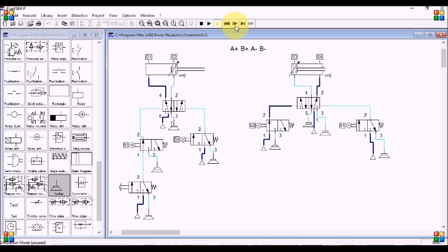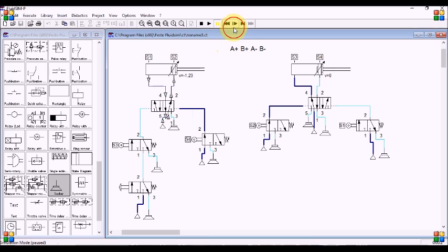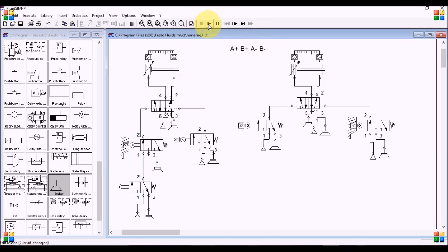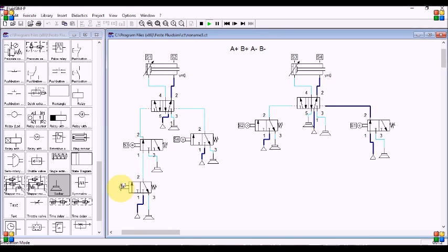In the next segment, again S2, as S2 is true, this makes position over here. So B plus happens, A plus, B plus. As B plus is true, we have to go for A minus. Let us have a look, yes, S4 is true. So A minus has been achieved. After A minus, it will go for B minus, S1 is true, then it will go for B minus. Just at a glance, if I click it, A plus, B plus, A minus, B minus.